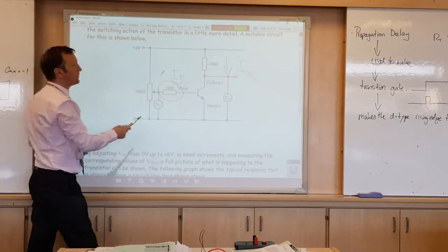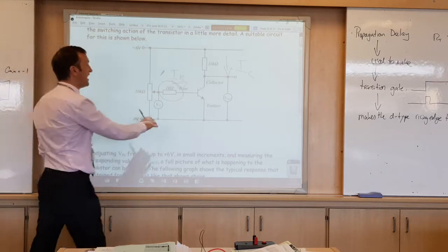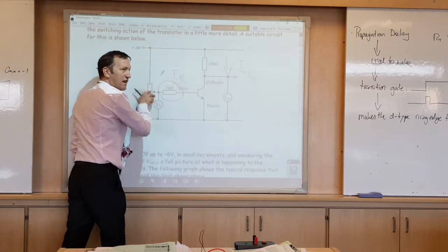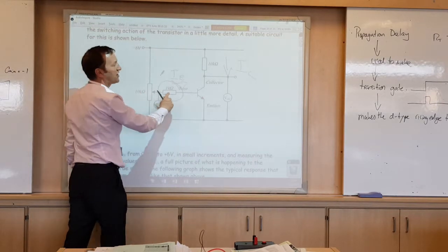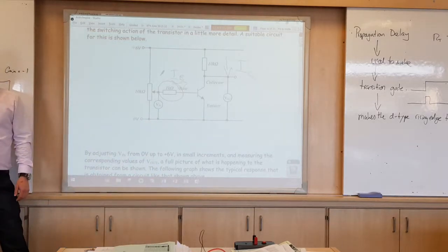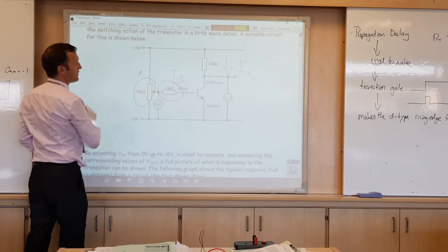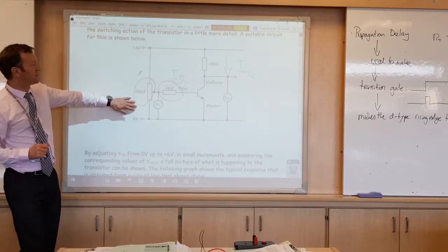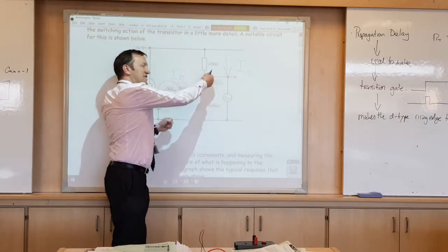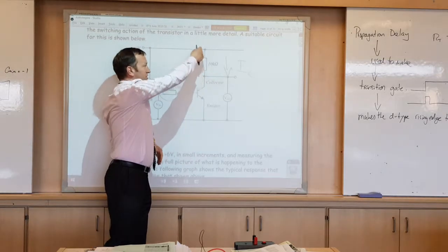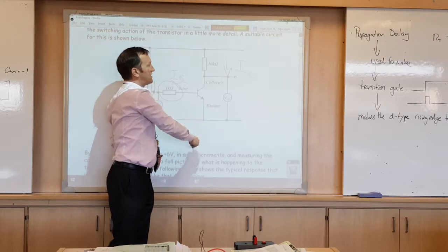The resistance of the current flowing into the base of the transistor is low, which means if you don't put a resistor there, it will suck current out, down through there. It'll affect your potential divider if you've got one of those. It'll load that too much, but also you can end up overheating the transistor. Okay, so we always have a resistor connected to the base. Here we've got a potentiometer to vary the voltage. So as we're going to increase the voltage here, the current's going to start flowing into the base. That's going to open the taps. It's like a big sort of tap, and the current's going to start flowing through the collector into the transistor and out of the emitter there.